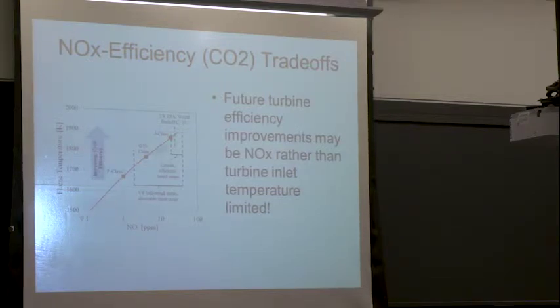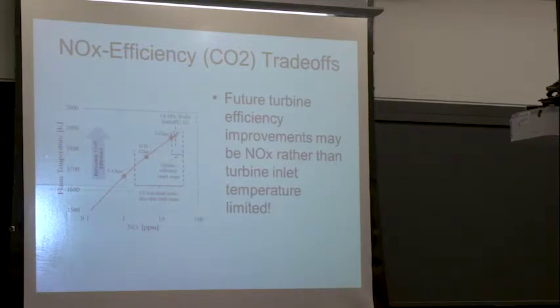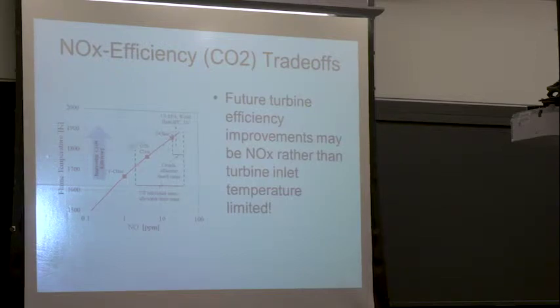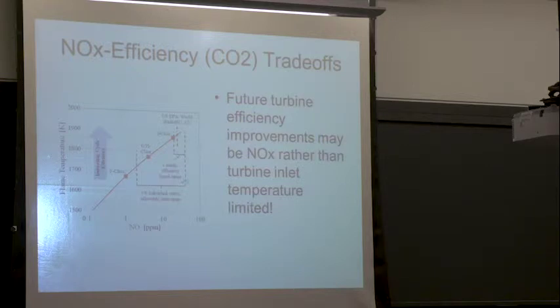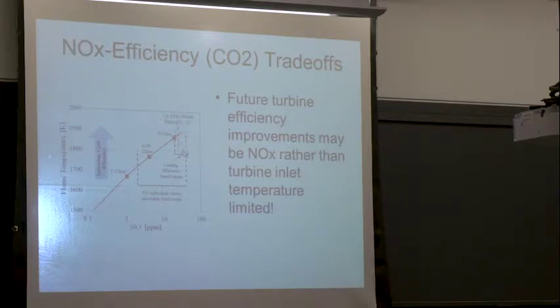And what I've put on here is just different classes of engines. This would be older technology, newer technology, really, really new technology, and how it's going up in flame temperature. What I also have here are some lines just showing some different NOx emissions. So sort of the range in the United States is between 3 and 30 parts per million. This is the range in Canada. This is the World Bank number.